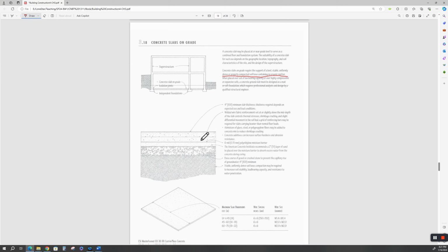You have your typical small residential house, 4-inch slab, and I'll fire the builder if he uses welded wire fabric in my house. I want reinforcing steel, not welded wire fabric. There's a vapor barrier that keeps your concrete slab from sweating. And this is 2 inches of sand compacted, and then some kind of granular material. Now, we don't use a lot of granular material down here. We use a lot of sand if they've got it.